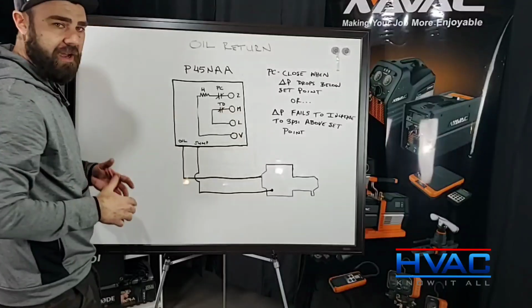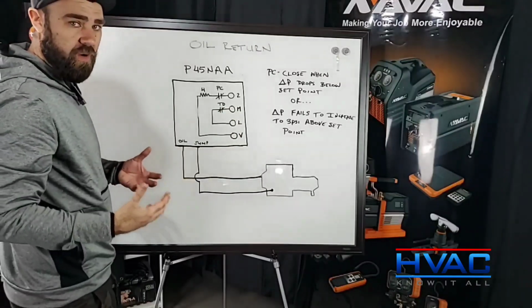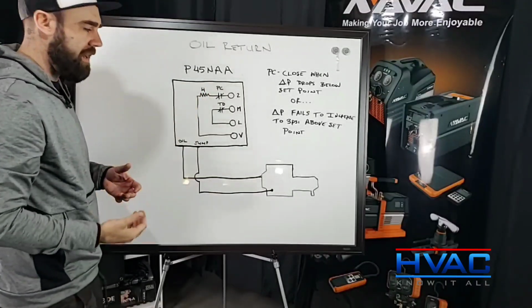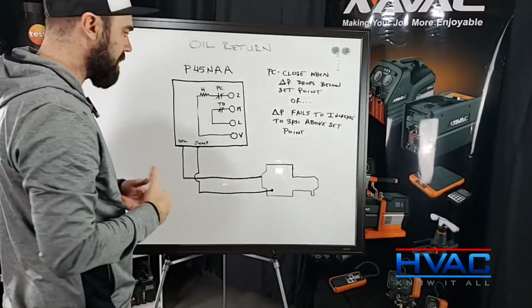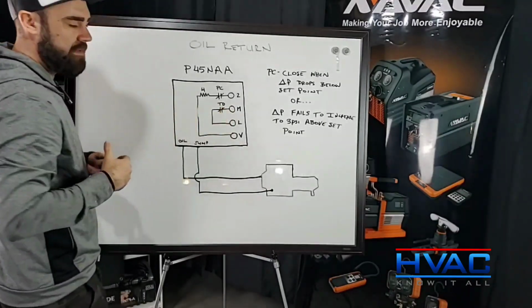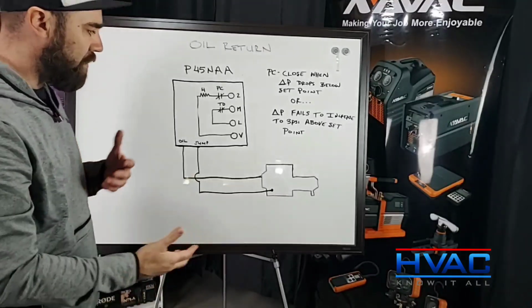This time delay contact will never ever open because this heater is now out of the circuit, and the heater is what activates the time delay, almost like a sequencer, if you guys have ever seen a sequencer. If this doesn't open, the compressor continues to run. So now we're happy, we're running.